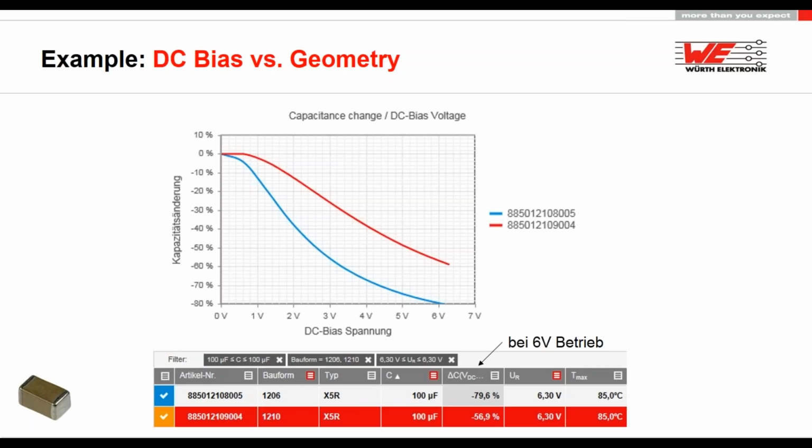This means if you get close to the rated voltage, please keep in mind that you lose a lot of capacitance, and it's not anymore the capacitance you know from the datasheet. And as you can see, with shrinking, this effect is getting worse. Integration density is a topic today, so if you go for new designs, it can be problematic when you shrink something and go for smaller types, because you get worse effects just by the selection of smaller types.